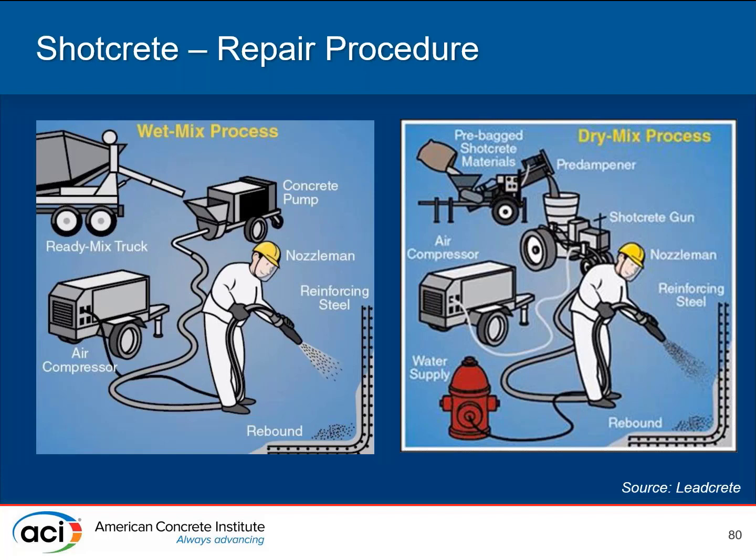One of the biggest drawbacks of that is you can get some rebound, where you're spraying it against the surface, and some of the stone and sand will bounce off and you end up with a big pile of stuff at the base of your repair area. The wet process is really good when you're doing large areas, because you can get the ready mix truck and everything's wet and you can just go and go and go, and it's a lot more convenient that way. The dry process is frequently used and a lot more convenient when you're doing small areas or a bunch of small areas.